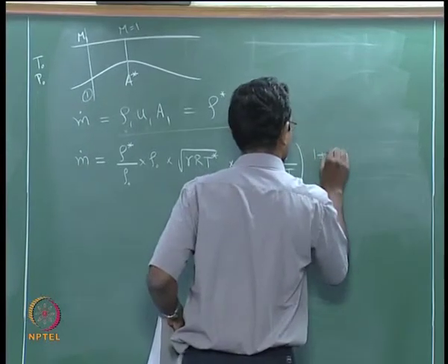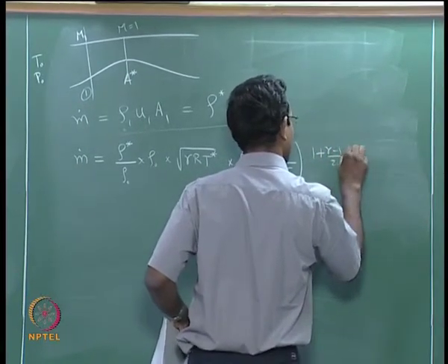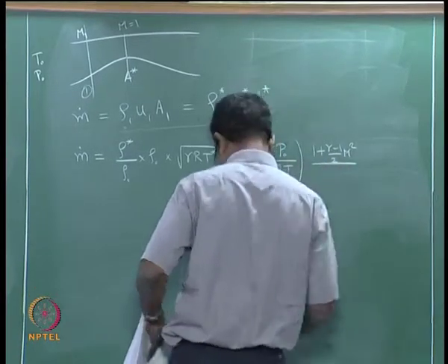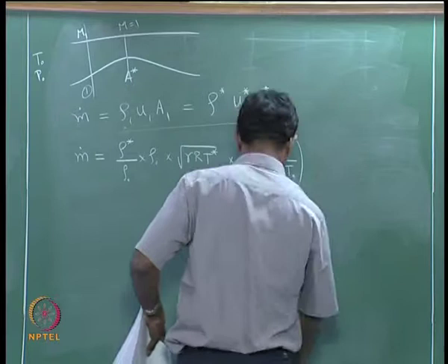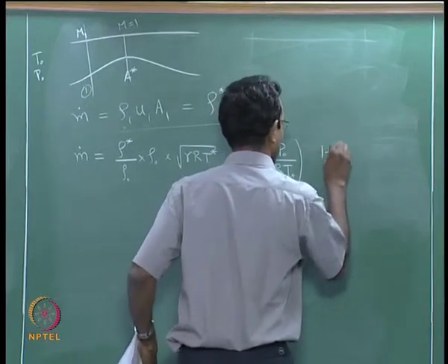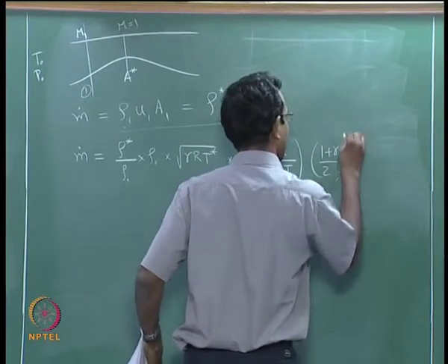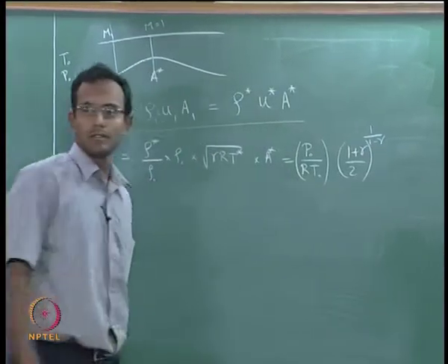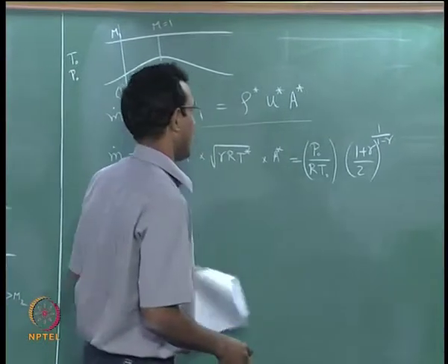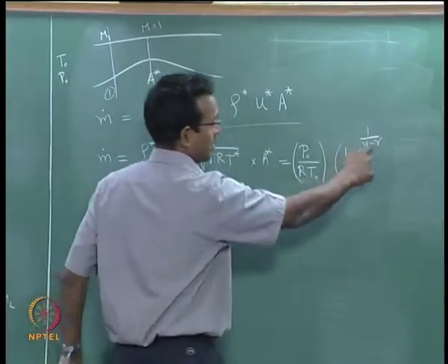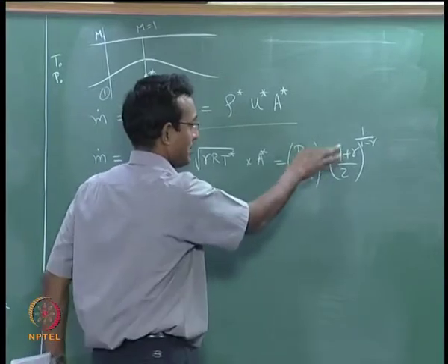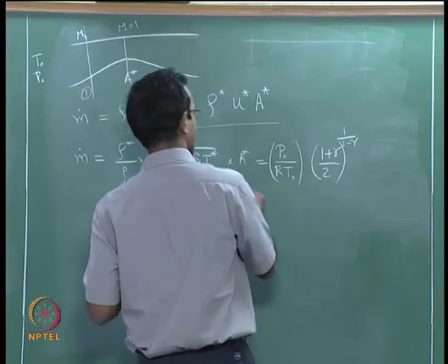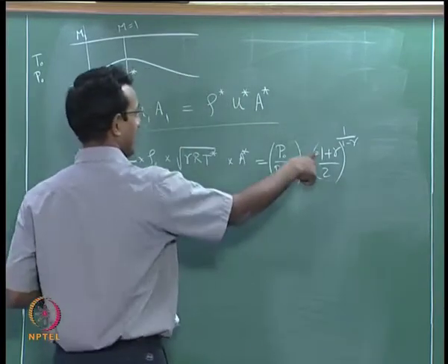That is going to be one plus gamma minus 1 over 2, for M equal to 1, it is just 1 plus gamma divided by 2 to the power 1 by 1 minus gamma. Okay. That is the function I have. Of course, I put 1 minus gamma here instead of 1 by gamma minus 1 because it has to be the reciprocal of that. Okay. I have already taken care of that. That is my rho naught multiplied by rho star by rho naught.